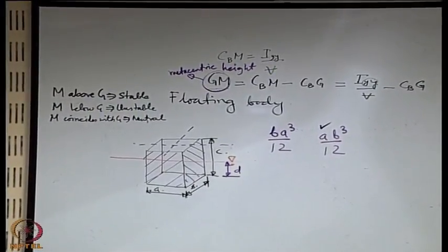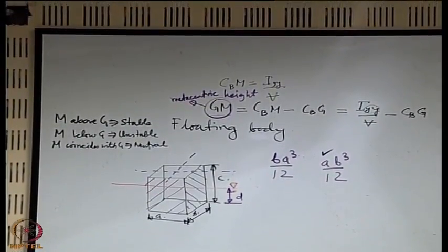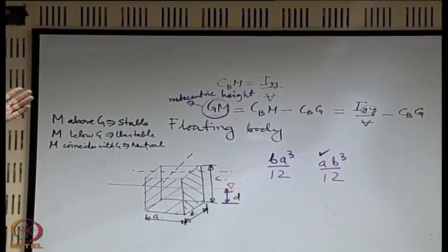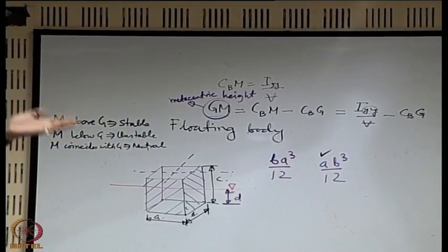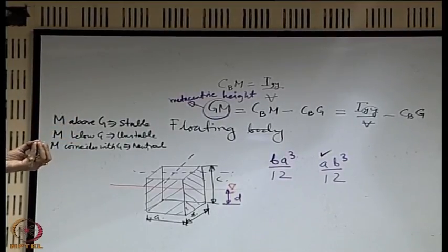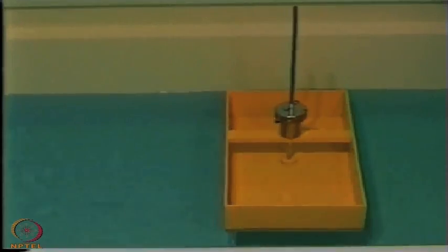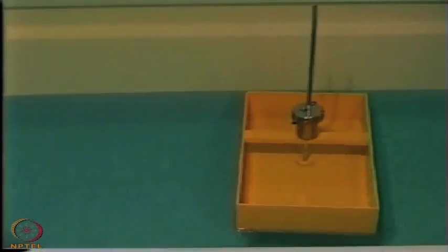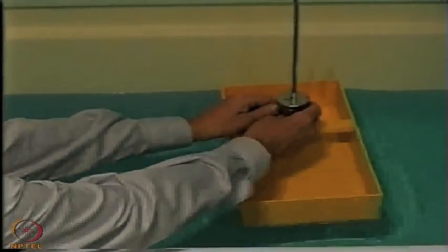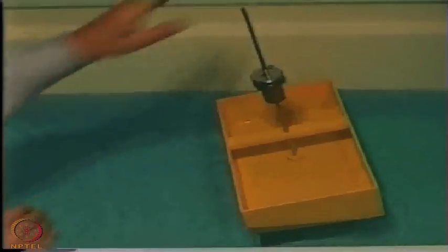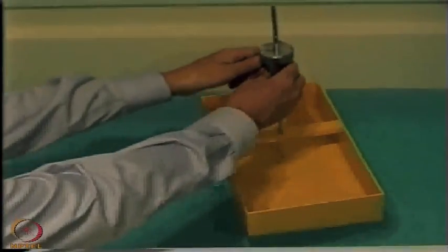There is a body which is given a slight displacement, and you will see that for small displacement it oscillates like a pendulum. We may easily derive the time period of that. Now you see that the distribution of the weight is being altered, so the center of gravity is being shifted higher and higher by putting the load more and more towards the top, and you see that it topples. So obviously this is a clear illustration of the concept that we have learnt: if you have the metacenter above the center of gravity, it makes it more stable, and otherwise it is not so.